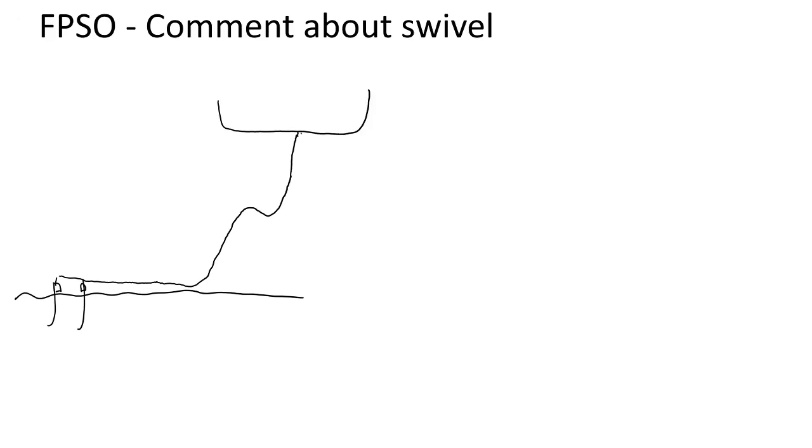So one thing is that the riser will have significant movement in this location, because it's going to be attached to some point in the FPSO, and then the FPSO is going to move up and down, and it's going to move left and right, like that. And not only that, but the FPSO is not always going to be oriented in the same way.